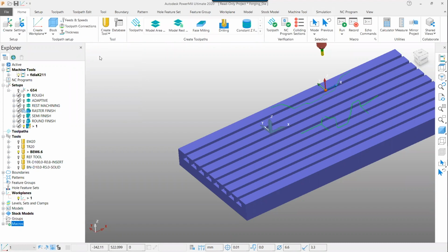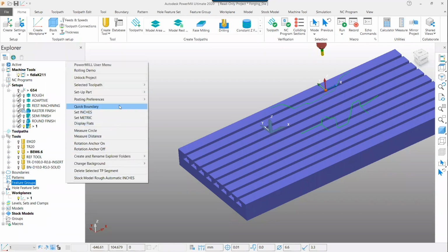But I've seen customers go as far as creating a setup macro, right? You have your part, you specify exactly where you want that setup to take place. So you can specify, hey, I want my coordinate system to be on the top of the model. And they have a macro that actually creates the entire setup. It creates the block for them, creates their safety planes, all with one single click. Just one single click is all it takes to do some of these options.